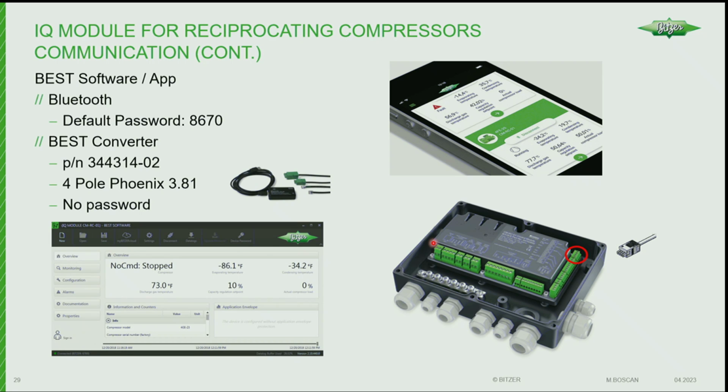So if you're going to connect hardwire, you pull this little plug here in the top right corner, find the correct adapter piece, plug it in, and log in, connect via your computer. That corner is also the location of Modbus. You'd probably have 4 wires coming out of that Phoenix connector. You either have to connect via Bluetooth or disconnect the Modbus to connect your tool, one of the two options. If you disconnect your Modbus, you're probably going to get some errors on your controller somewhere about communication errors, so just remember that.